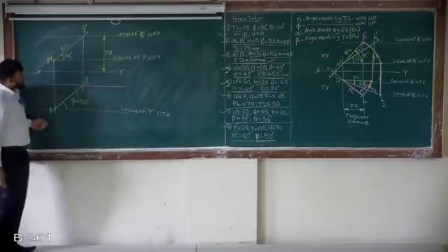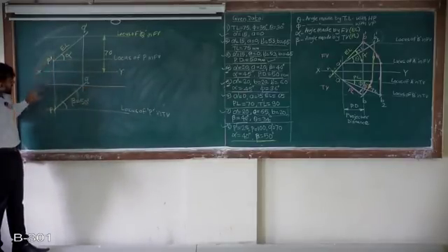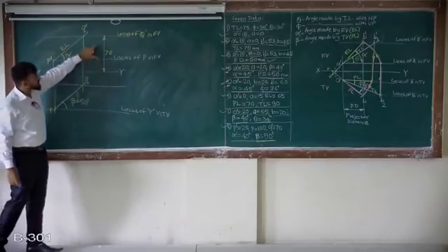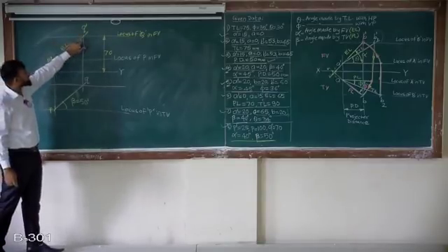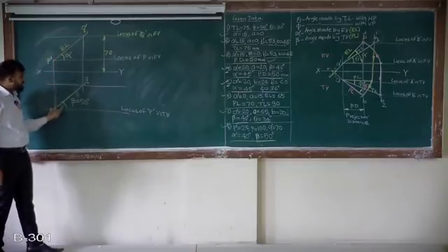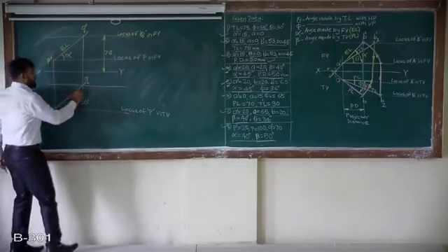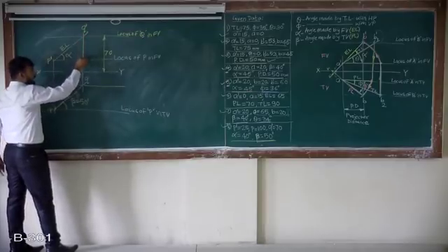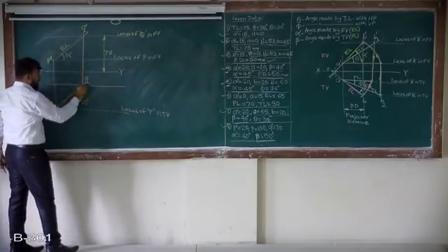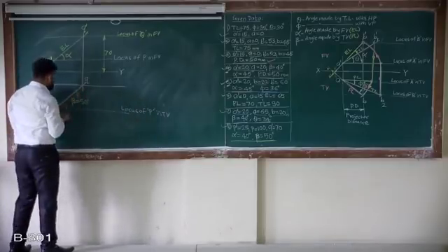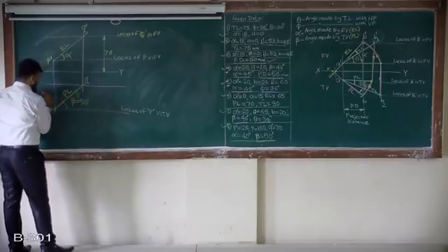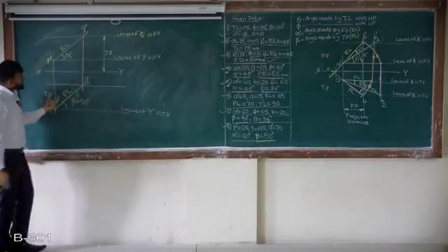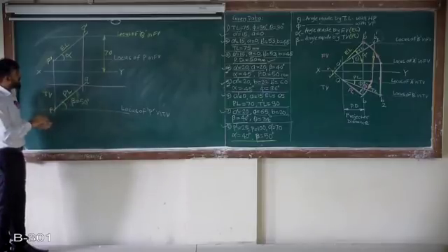Draw the locus. Say I was knowing P dash 25, I was knowing P 100, so I drew the two locus. Q at 70 mm, so from XY 70 mm. I was knowing angle alpha, so I marked alpha, I got the point Q dash. At point P I marked beta like this. Just drawing a projector, I will get point Q. So once you know EL, this is the plan length as top view. So how to get the true length? So that's whole problem now.